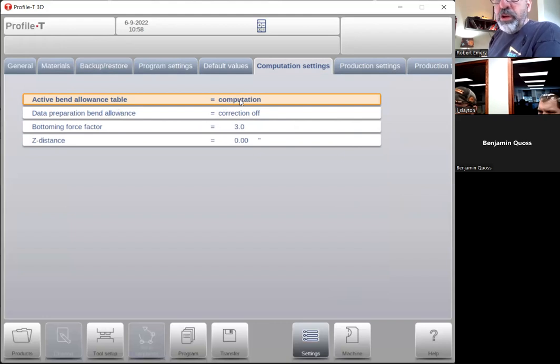And there's a way to do it through the auto screen that's even easier, because it'll fill in a lot of the questions it was asking. It'll know what material, it'll know what the angle is, it'll know what the tooling was. You just give it what the correction was. Okay. So it's even easier in the auto screen. But it'll build up this table with all your setups, all your materials, and these angles and what the correction was. Okay. Cool.